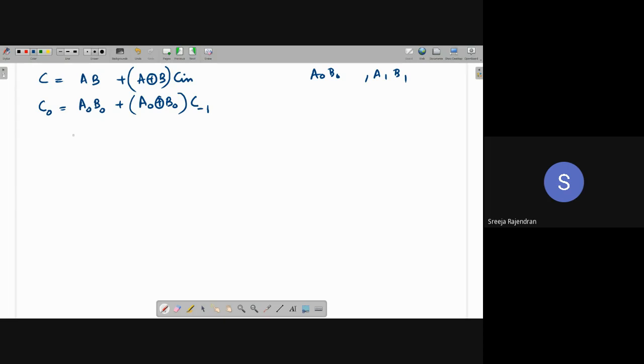So now I have written my carry expression in terms of, this is something, I have a term for this, I call it generate. I can generate AB, right? If I know the input specific bits, I can generate AB. I can also generate A XOR B. That is called propagate, because that has to be ANDed with the carry. So I call it propagate.